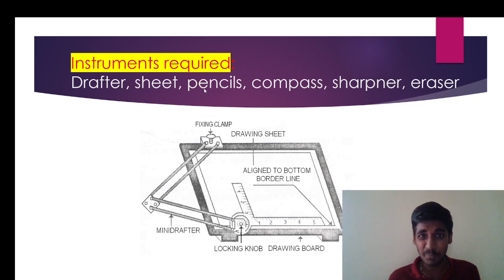Clarified? Next, coming to pencils, as I said in the last video, you must use 3 pencils. Apsara and Atlas are the main preferable companies of those pencils. I'll explain in the next slide. So H, as you may already know, HB, 2H: these are the 3 pencils you should use in engineering graphics. HB pencil is for the output.